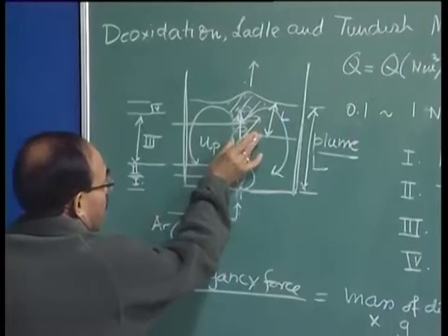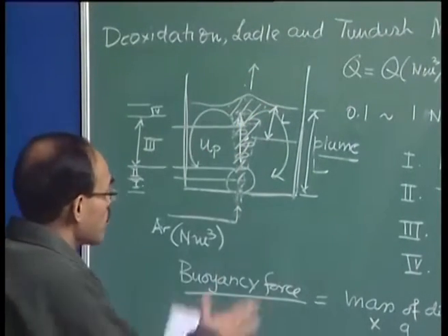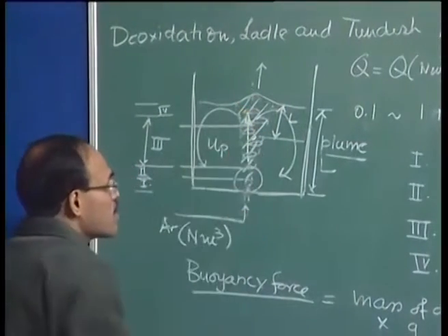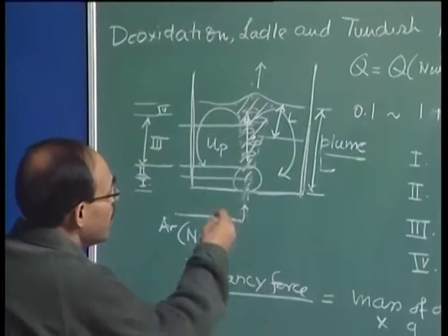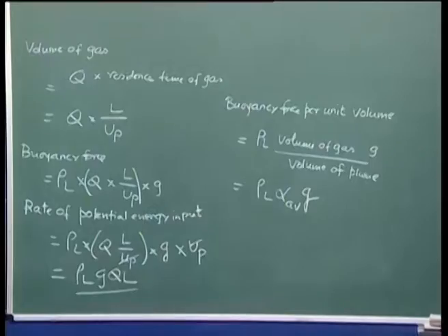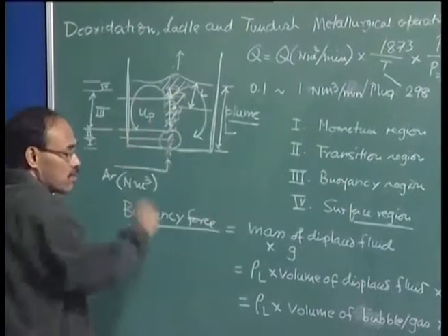So we have the gas volume fraction continuously decreasing as the plume would expand towards the surface itself. So there is a variation of gas volume fraction within the system, but we would say that we can average it out over the entire volume, and this alpha average, whatever I have shown towards the right, is actually the mean gas volume fraction of